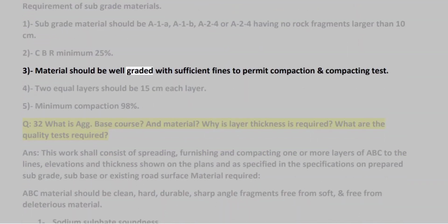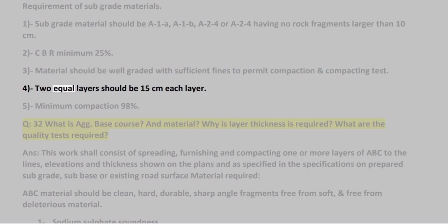3. Material should be well graded with sufficient fines to permit compaction and compaction testing. 4. Two equal layers, 15 cm each layer. 5. Minimum compaction 98%.